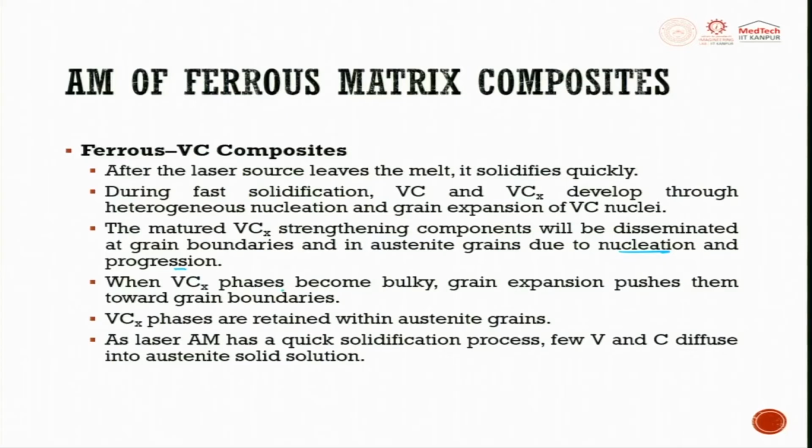When the VCX phase becomes bulky, grain expansion pushes them towards grain boundaries. The VCX phases are retained within an austenitic grain. As laser AM has a quick solidification process, a few V and C get diffused into the austenitic solution, as a solid solution.